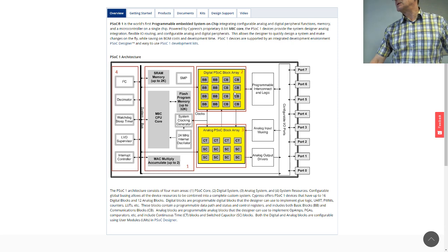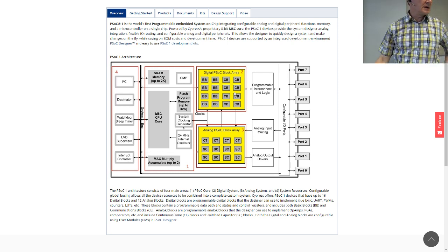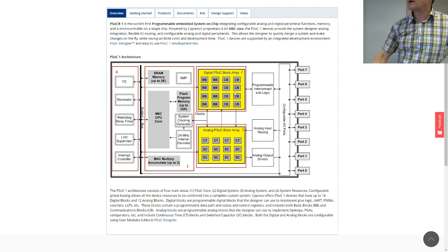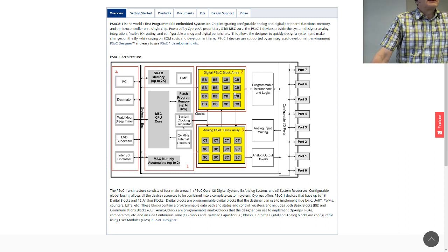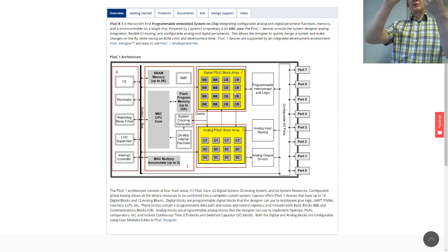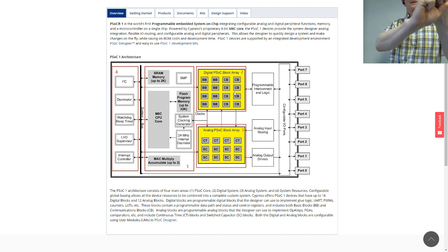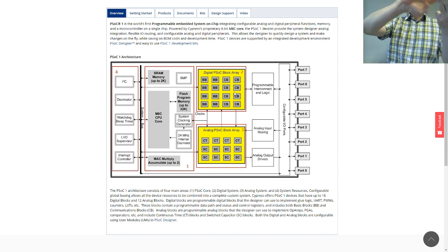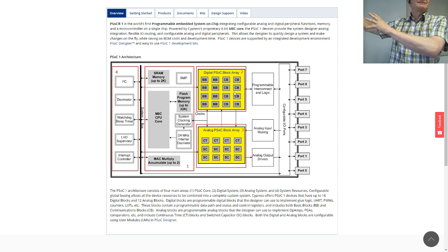The digital block arrays you can find, I think, in Texas Instruments circuits too, but what is really unique for Cypress PSoC is that there is also this analog block array, both continuous time and switch capacitor type blocks, meaning you have programmable amplifiers, programmable multiplexers, programmable analog filters, and of course different types of A to D converters and D to A converter possibilities in the same chip.